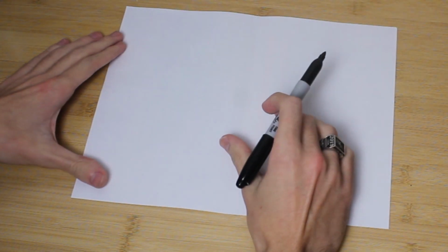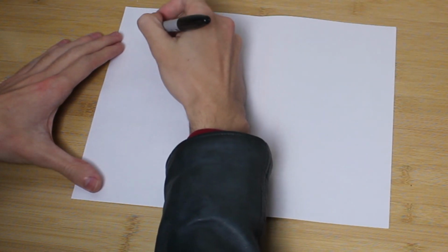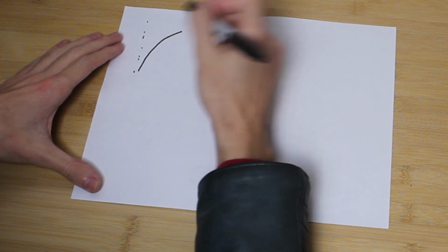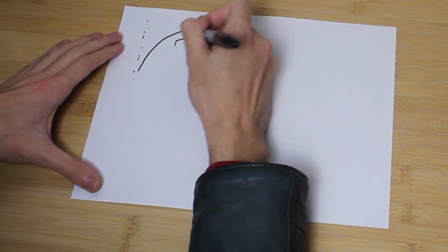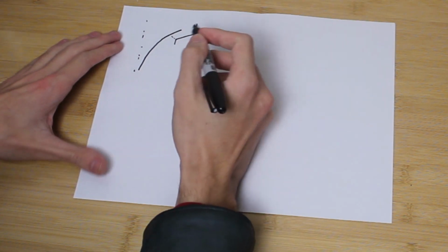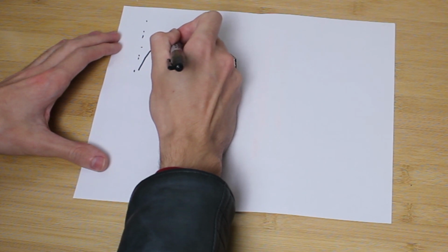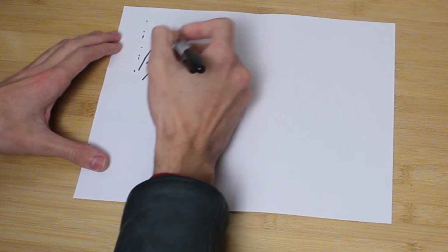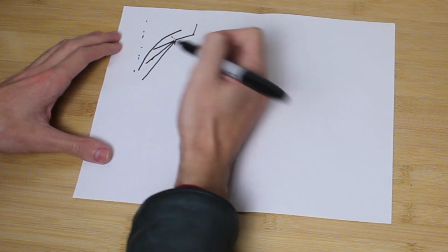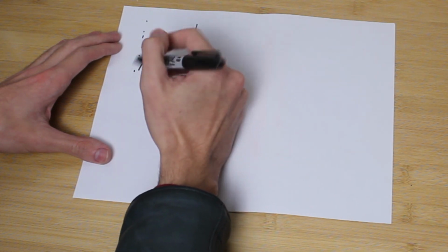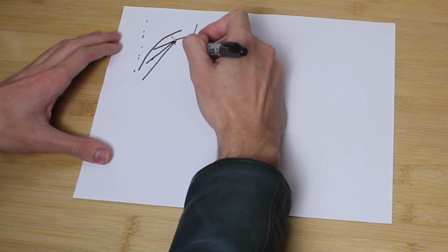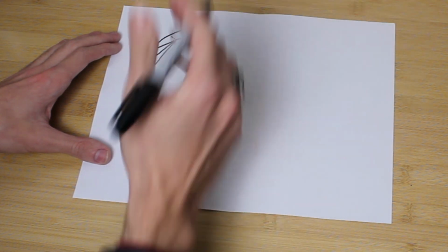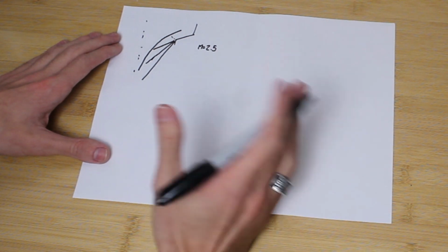Alright, this video is getting a little long, so let's wrap it up. So what we've got here is the center line of our toroidal aerospike that forms some shape contour like that, that has some shroud, that forms some throat plane. And we've got our simple region of expansion fans that come out from the end of our shroud, like this, where each of these lines represents a Mach number. And we're going to pick a Mach number for the total length of the spike. So for example, in this case we could say Mach equals 2.5, which would be a fairly typical Mach number for a rocket engine.